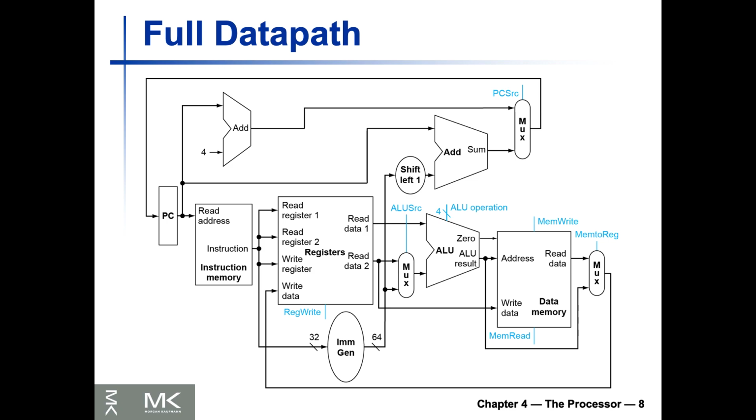Program counter. So when you start, for each of the lines, it's going to add +4, or if it has to branch, it's going to branch to a destination address again. If not, it's going to come back and add +4, and then it's going to go for the rest of the program.